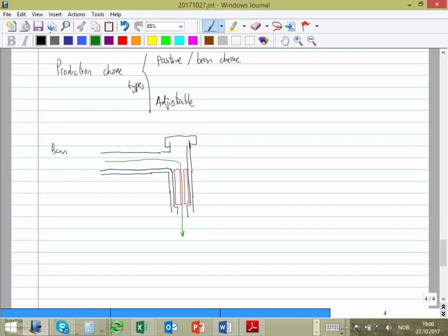And the sizes are typically something like 1/8 of an inch, and the length is typically around 6 inch. It might be shorter, but the space that you have available is like 6 inch. That's standard. And the sizes, this is the orifice size, the small opening here, goes from 1/8 all the way usually to 2 inch. It doesn't go in any size, but in steps of 1/64 inch. So you have 1/8 plus 1/64 and so forth.